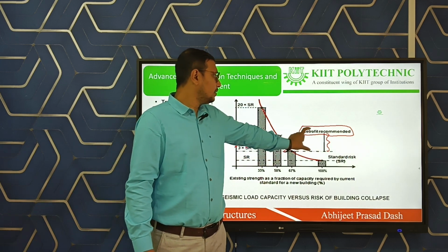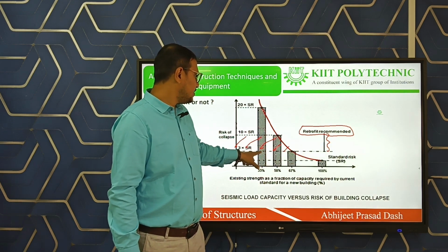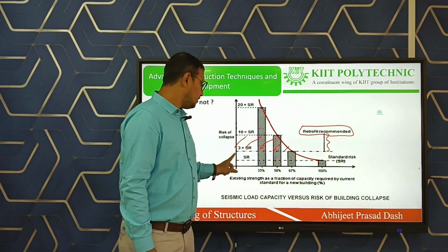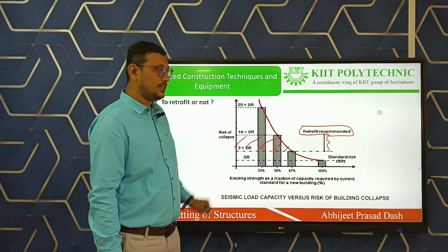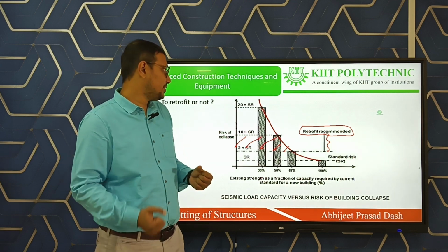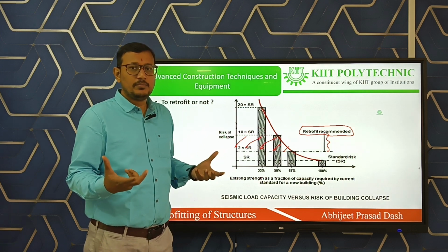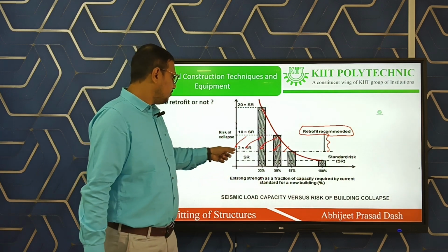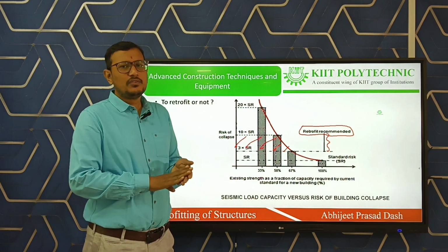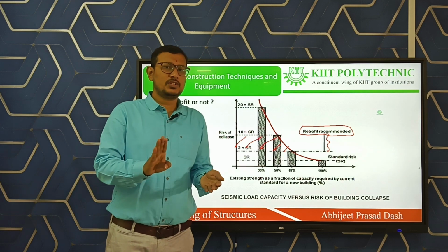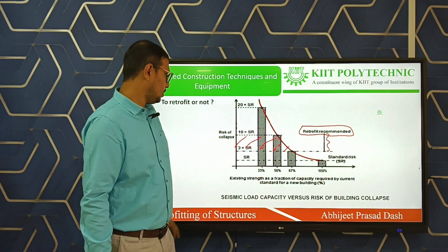In this region marked in red, from this to this region, we can go for retrofit. Above this it is a waste of time and money, we cannot go for retrofit. Below this it is not required, it is standard risk. To resist the earthquake, retrofitting is not required, only restoration of the structure is sufficient to take the earthquake load.